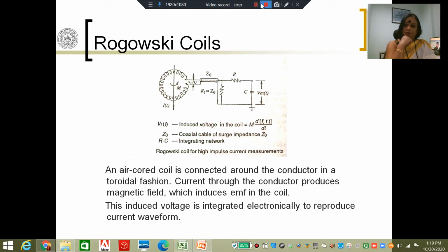So far, we have talked about the conventional electrical measurement technique for PD. In the conventional measurement technique, we try to register the current pulse that is produced due to partial discharge happening inside an equipment, and we try to measure that using electrical circuits. But we have also seen that there are various problems associated with such measurements. Most importantly, we have talked about a very low signal to noise ratio, a lot of noise, a lot of interference. And one of the most important problems that we have not talked about so far is location.